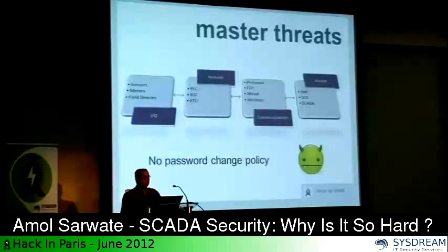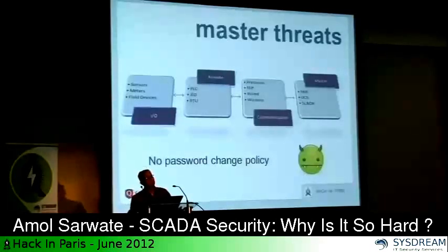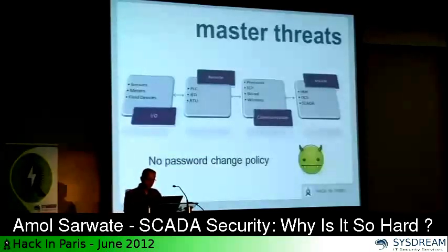When asked why they don't have passwords, the number one response that I received was that these are critical systems. If there is, for example, a fire in the plant or something like that, they don't want operators to type in the password, oops, wrong password, type in again, wrong password, because they have to respond immediately. That is okay, but at one of the SCADA conferences that I was talking at, there was a person from the military, and he said, well, we have 18-year-old people who type in 25 character long passwords which are changed every two weeks, and they never miss it.